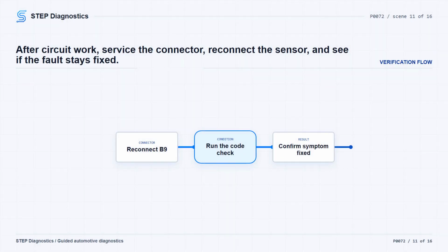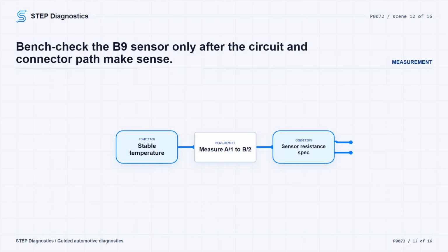If the scan tool ambient air temperature parameter is negative 35 degrees Celsius, negative 31 degrees Fahrenheit, or colder, connect a 3-amp fused jumper wire between signal circuit terminal A, or 1, and low reference circuit terminal B, or 2. Now the scan tool ambient air temperature parameter should be greater than 143 degrees Celsius, 290 Fahrenheit. If it is 143 degrees Celsius, 290 Fahrenheit, or colder, turn the ignition and vehicle off and remove the jumper.